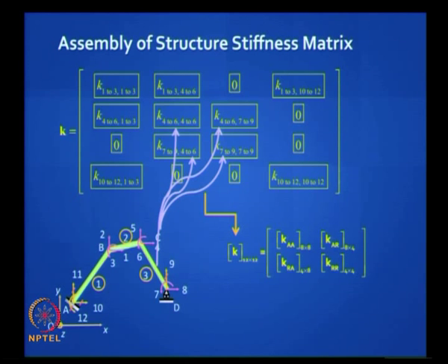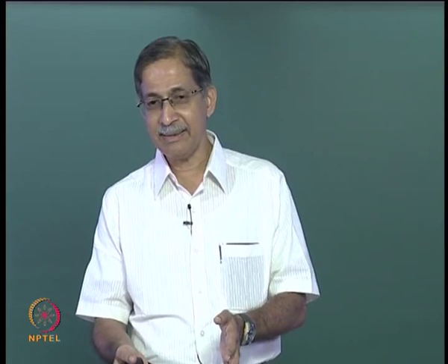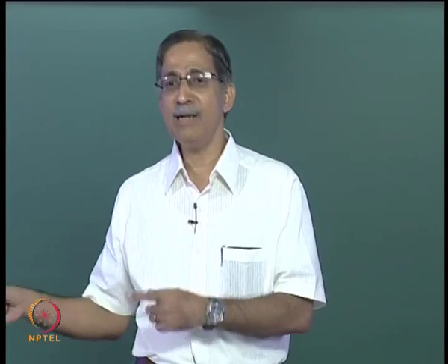Finally, after you have got this matrix, and we will see that there are many other ways of getting the same matrix. There is a reduced element stiffness method, there is another method which we will study soon of getting this matrix, because this has a big advantage that you are playing with little boxes. No matrix is more than 3 by 3, so your storage is very elegant, economical. Only thing, you must program it well so that it goes to the right slot. There is a crude way of doing it, we will look at that for beginners, that you will be more comfortable with, but when you do programming, when you want to solve a very large problem, you can't do that, that is too unwieldy.